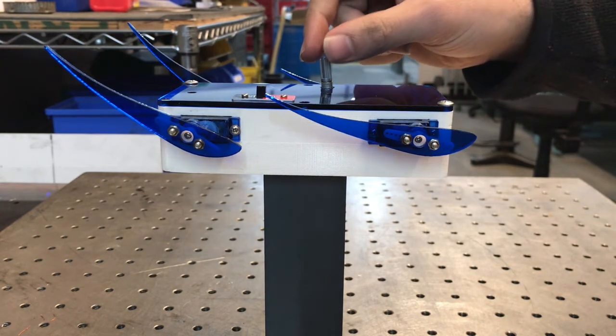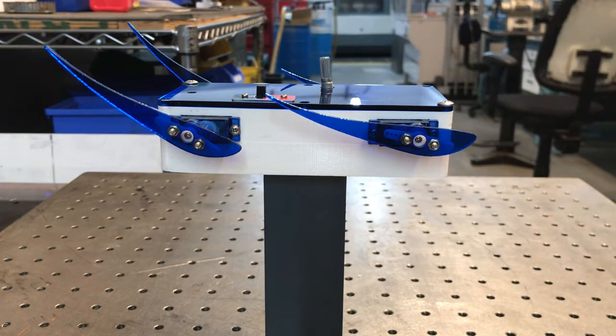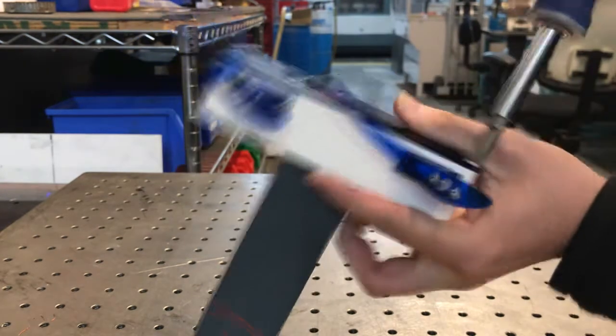In the middle here, there is a knob, a potentiometer, which is our way of abstractifying numerous car variables, such as wheel speed, steering angle, etc. But our main data acquisition is through the IMU in the center here, which is collecting X and Y acceleration. So let's open this up and see on the inside.